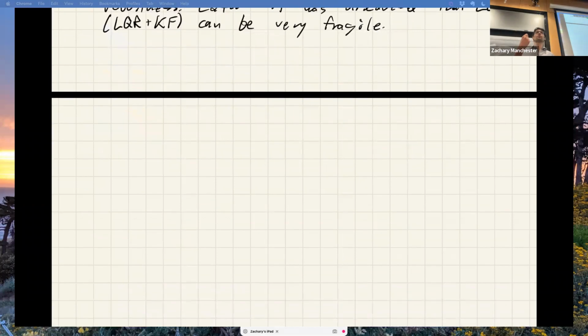No, not noise, model error. If I write down my A and B matrices for the linear system, the measurement model and dynamics, and A is a little bit wrong, for example, and there's some perturbation to the system dynamics, which corresponds to getting the length wrong or the mass wrong by a few percent, that's what we're talking about here.